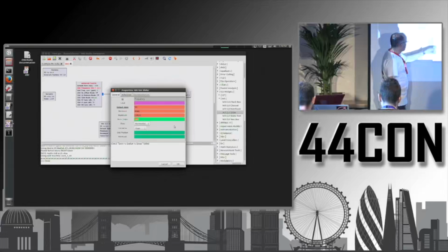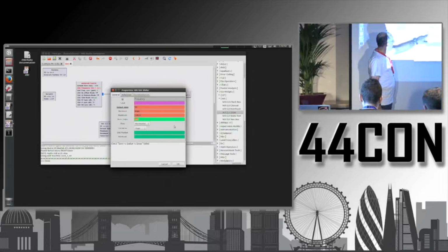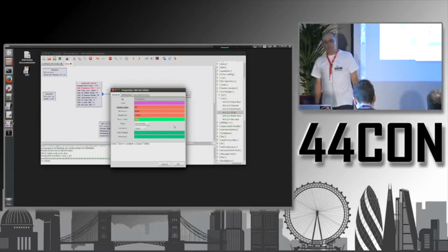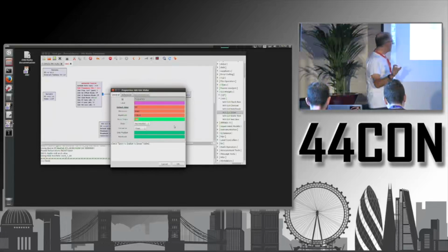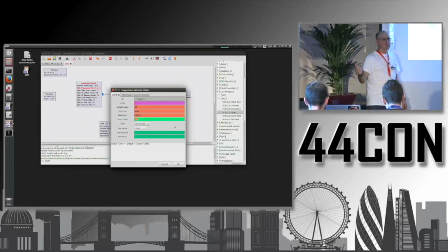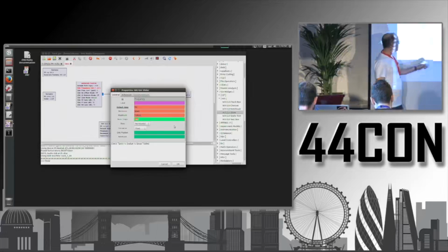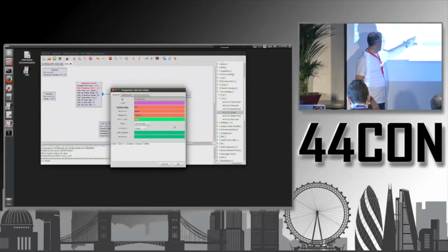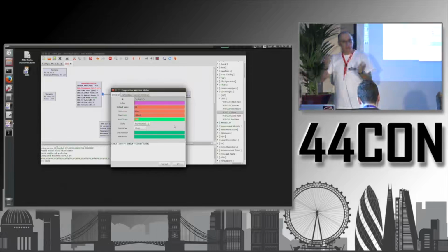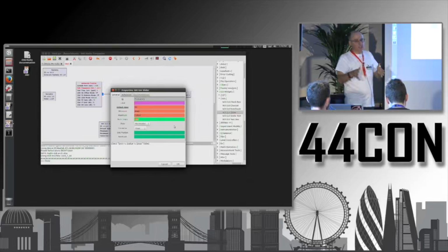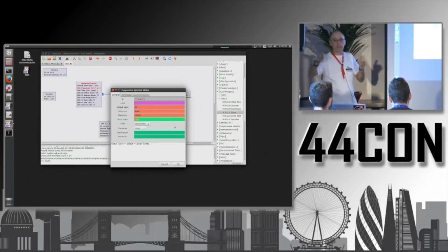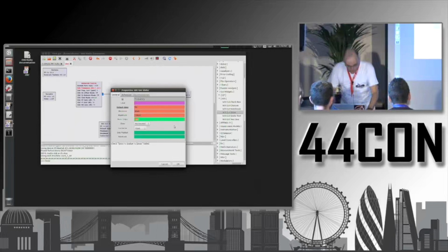So from 80 megahertz to 108 megahertz, that gives me 28 megahertz, and I want to be able to tune in with 100 kilohertz steps. That means here I can say the number of steps that I want between those two values. If I say 28, then I can go from megahertz to megahertz. If I say 280, 10 times more, then I can go from kilohertz to kilohertz. So that's what I'm going to use.